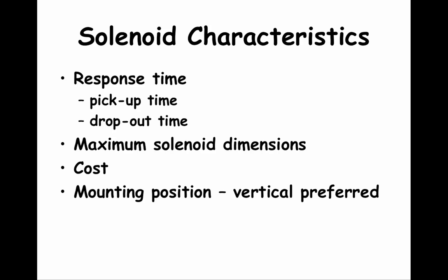Similar to the discussion about relays, solenoid response time when energizing, which is called the pickup time, and when de-energizing, the dropout time, can be important in some processes. Other things to consider include the solenoid dimensions, cost, and mounting position.